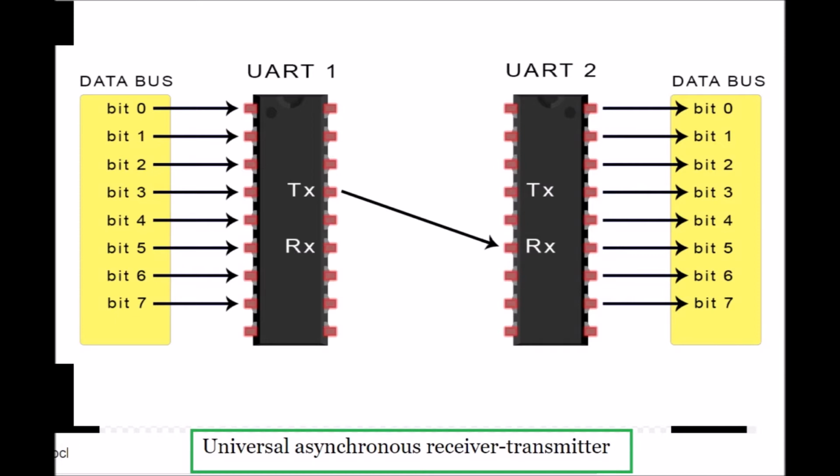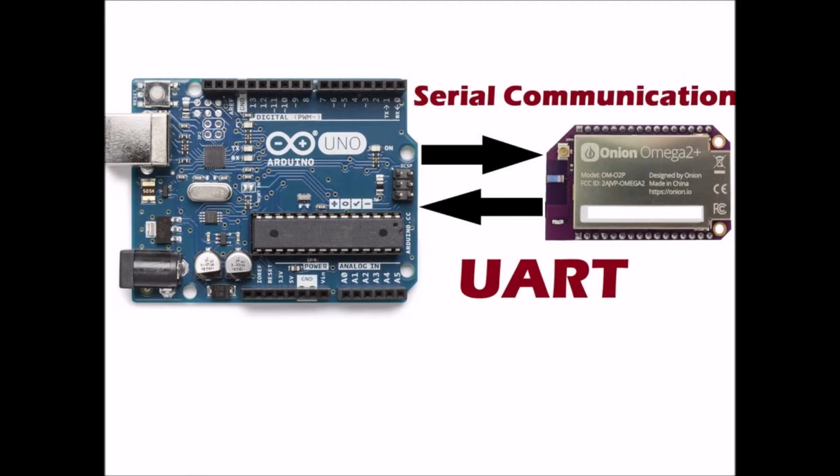A UART is usually an individual or part of an integrated circuit, IC, used for serial communications over a computer or peripheral device serial port. One or more UART peripherals are commonly integrated in microcontroller chips. A related device, the Universal Synchronous and Asynchronous Receiver Transmitter, USART, also supports synchronous operation.